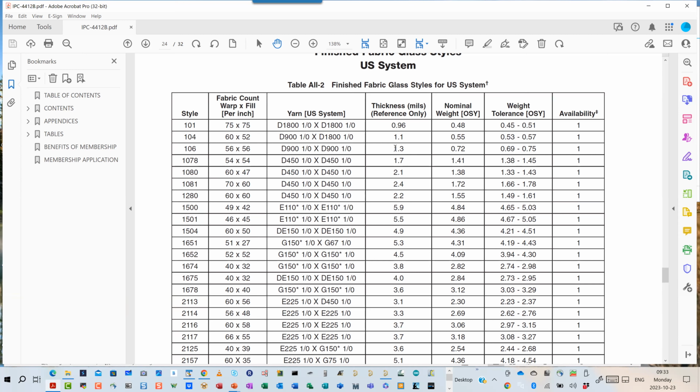Okay, so what we end up with is the sheet of 106 material is going to be thicker than the sheet of 106 glass, because it's the glass plus some resin of our resin system here, if that makes sense to everyone. But anyways, this is where those numbers come from. So when you talk to a fabricator, and your fabricator asks, I'm recommending that we make the board out of 2 sheets of 106 instead of a single sheet of 2113, this is what they're talking about.